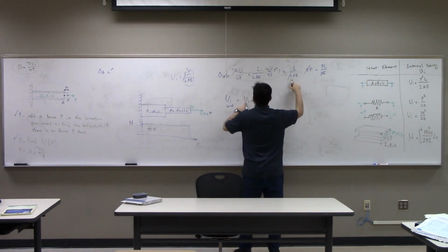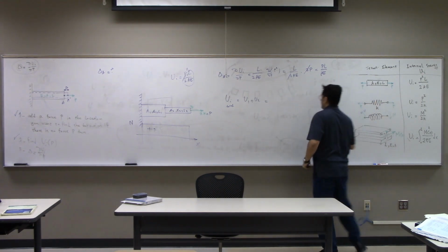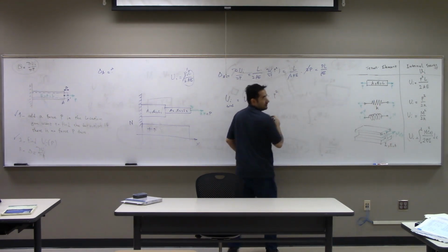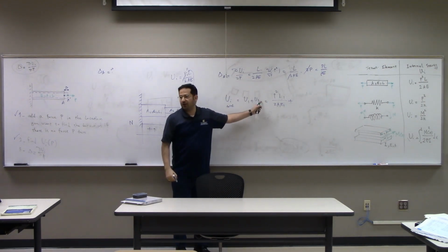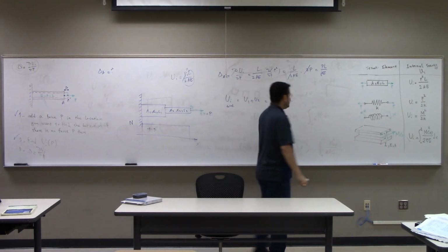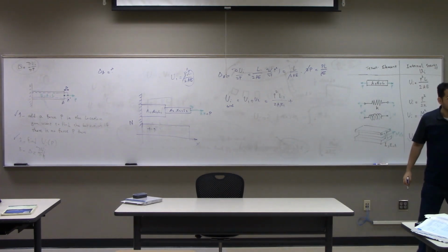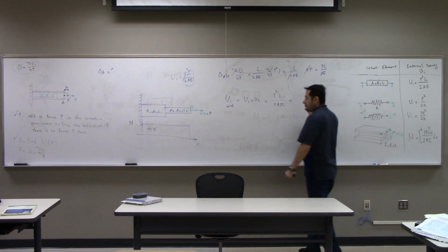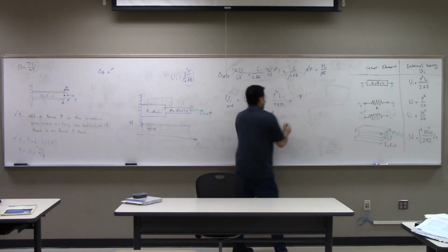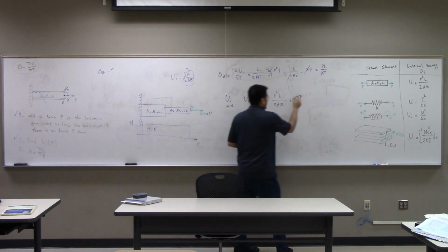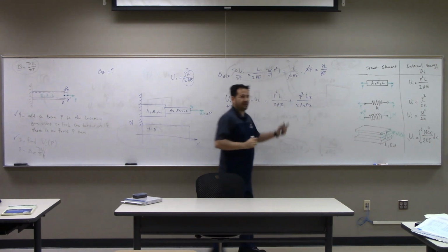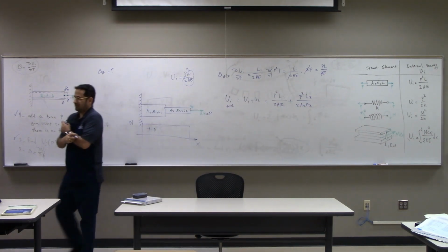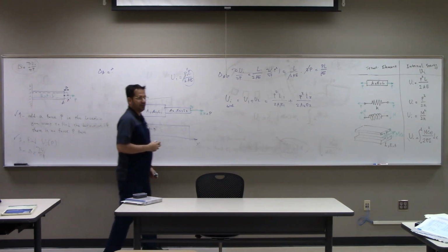So you put P. Instead of here U1, you put, let's use integration, P squared times L1 over 2A1E1. Thoughts? U2. What should I write for U2? Not the same thing, something like L2. The same formula, but you just use P again because the actual load is P. P squared, then you have L2 over 2A2E2. That's it. Right? So what would be my deflection then?